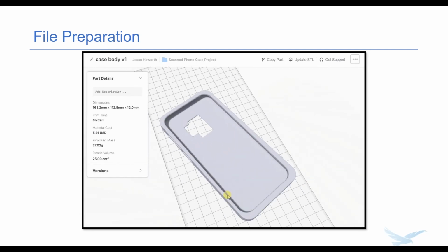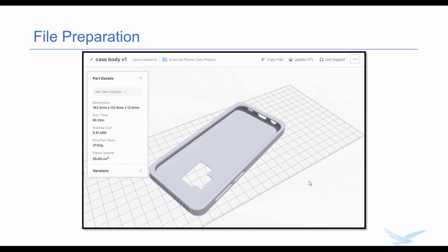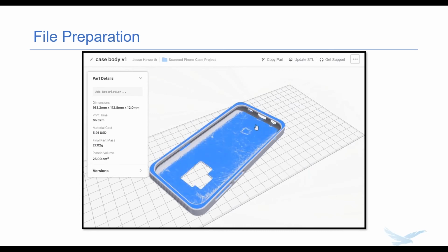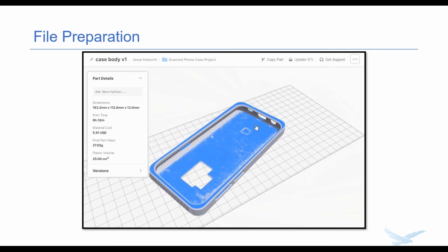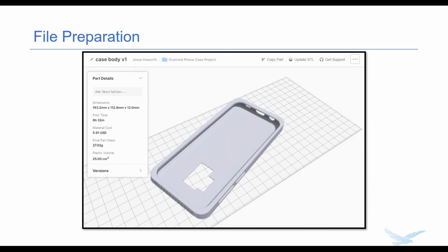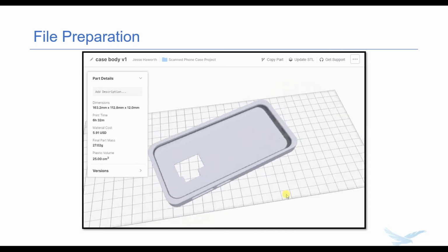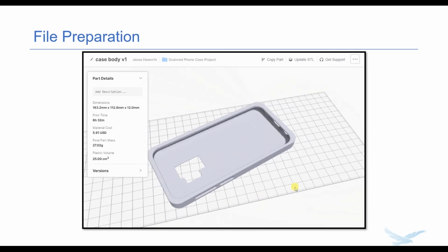Now, Eiger is what's known as a slicer, which means, again, that it converts or slices STL files into those extremely small layers that I talked about. These printers will, again, create parts layer by layer until their geometry is finished. The slicing is all automatic. There's no manual tool pathing of all the different layers. And for a part like this, it really only takes a few seconds to process.